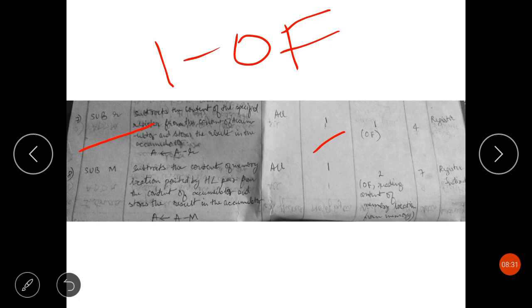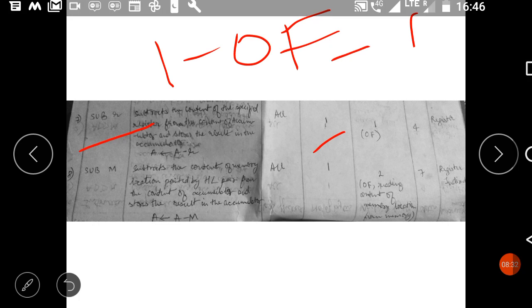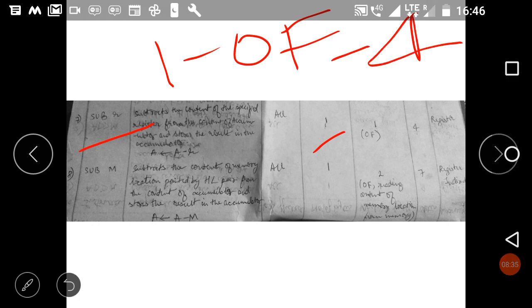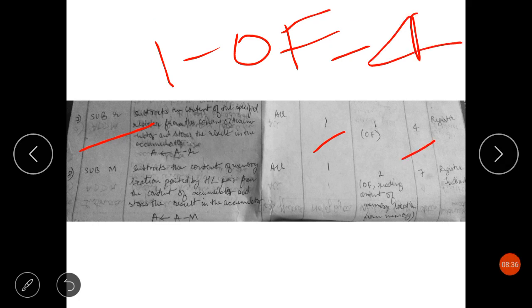T states: obviously the opcode fetch machine cycle will need 4 T states, so the total number of T states is 4 for this instruction. And addressing mode: obviously here the operand is the content of the register or the content of the accumulator, so the addressing mode is register addressing mode.